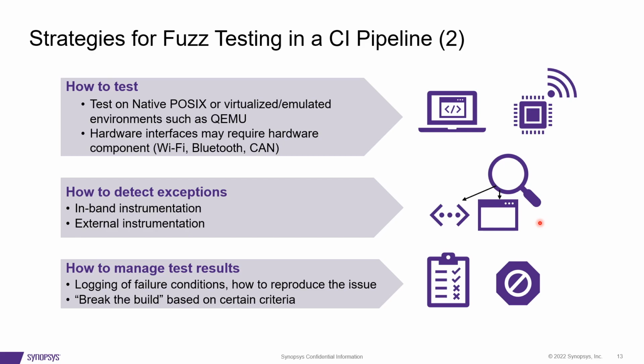Regarding how to test, we need to understand what is the best environment we can use. For example, can we perform testing on native POSIX, or can we use virtualized emulated environments such as QEMU? Or do we require hardware interfaces for certain hardware components, such as Wi-Fi, Bluetooth, and CAN?